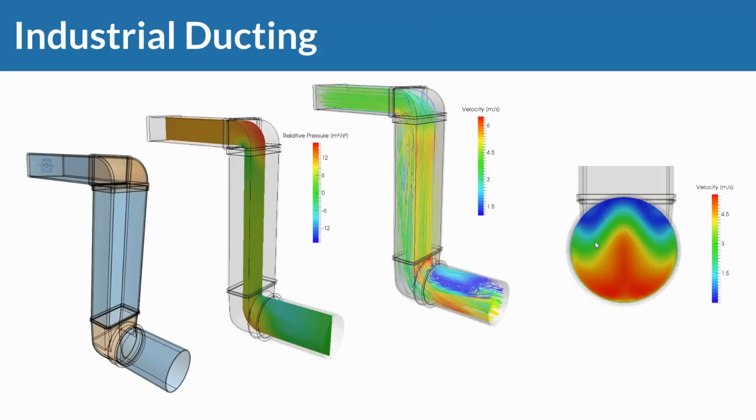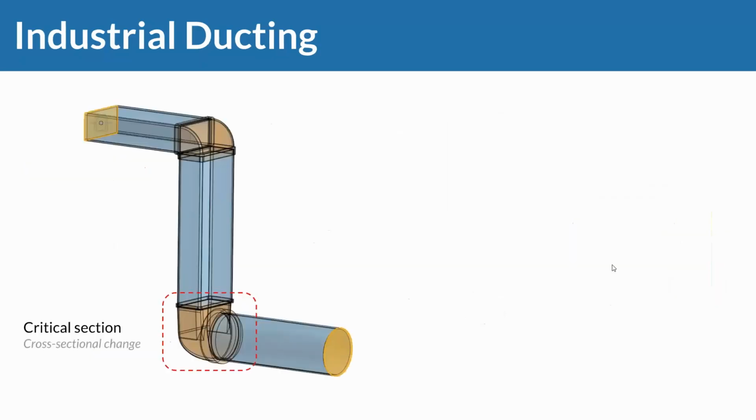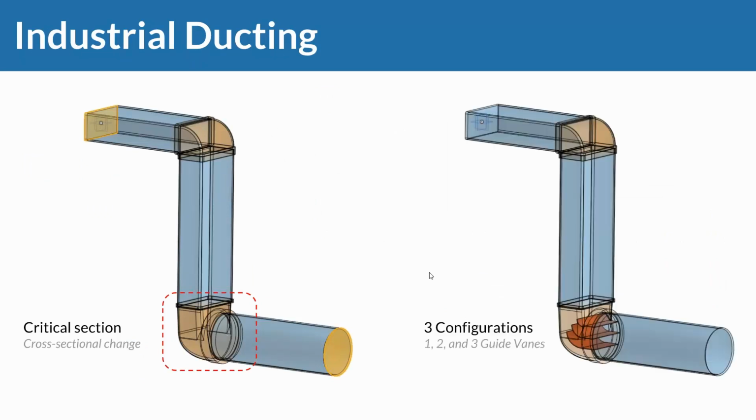And also interesting, at the outlet, I can see this qualitative indication that half of my flow path is effectively blocked. And what I can do now as an engineer or as an architect is say, okay, you know what? I have this huge recirculation area there at the bottom, so why not give it some guiding veins and help the flow around the corner, reduce the recirculation area, and hopefully have a more effective flow path.